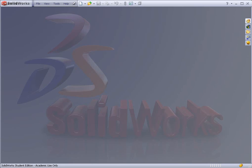Exercise 7. In this exercise, we're going to learn how to create a unique type of curve. It's called a projected curve. It actually takes its sources from two separate planes. In this case, we will draw something on the front plane, and then we'll draw something on the right plane, and where they intersect, they generate a three-dimensional curve.